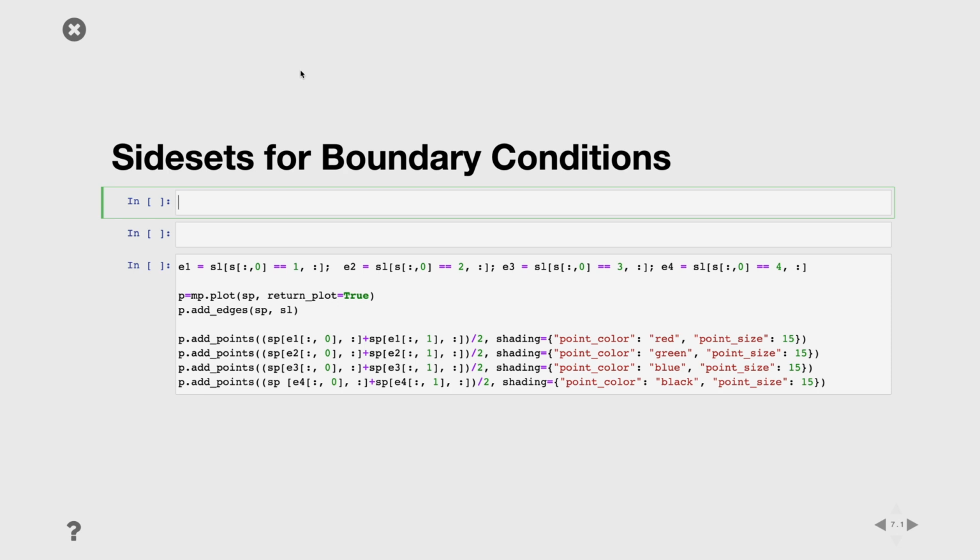So the way it works in Polyfem, there are two ways. One is the default one, and what Polyfem will be doing is automatically setting some number, the number of the side set, to facets or edges in this case, since it's 2D, touching the boundary. So we will have 1 for the left, 2 for bottom, 3 for right, and 4 for top. Everything that's touching the bounding box up to some epsilon will be automatically assigned with that. Another way in Polyfem to specify boundary side set and boundary condition is to use a lambda function. We will see that in a next tutorial.